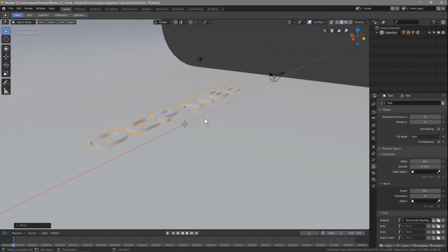The other way to do that, if I undo that, the other way to move an object is to click on the move tool here. And then you can see Z is here, right? This is the Z axis and it's highlighted blue. You can just drag it up by the handle as well. You can do it that way. But if you remember the shortcut, G is to grab, and then you can either move it X, Y, Z. And you just need to look at this little cursor up here to work out which direction you want to move. We want to move it vertically, right?